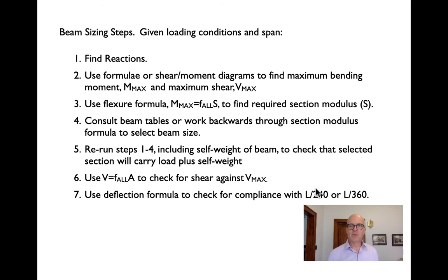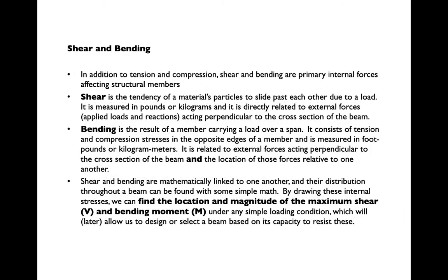And then depending on whether we have a deflection criteria of L over 240, relatively loose, or L over 360, relatively tight, we'll use the deflection formula again from the tables that I'll show here in a minute to check for compliance with deflection. So remember that shear is the tendency of materials' particles to slide past one another.